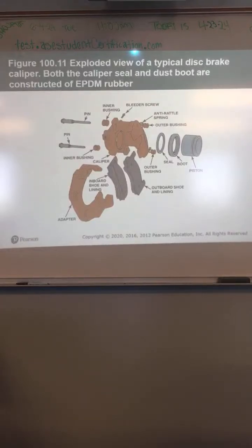In what case would you do that? Maybe a system that didn't have a brake fluid flush for a long time, or it just had been abused, or whatever. Okay. You might take them apart, clean them up, put new seals in them, stuff like that. Normally, you just buy a new brake caliper, like most of the time we do. Okay. It is possible to do that, just so you know.